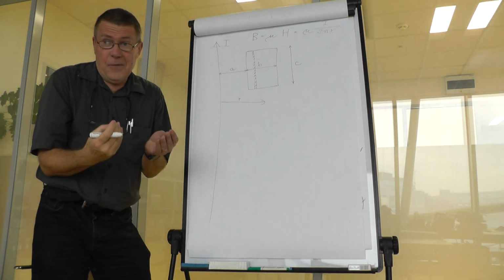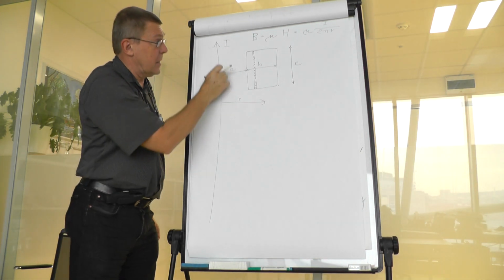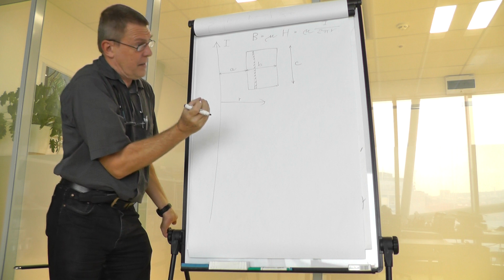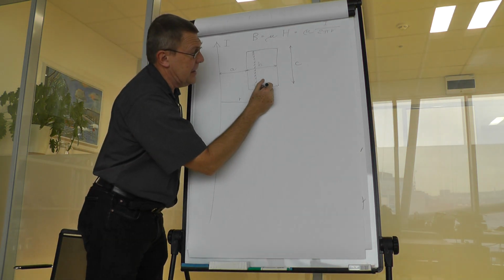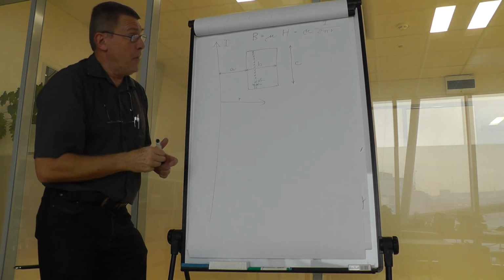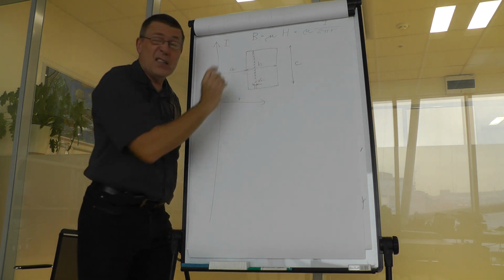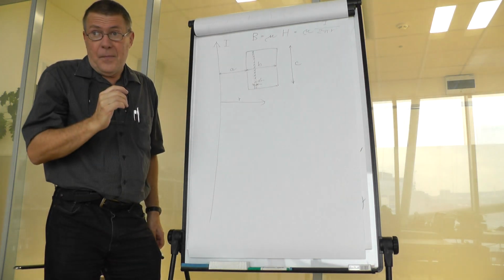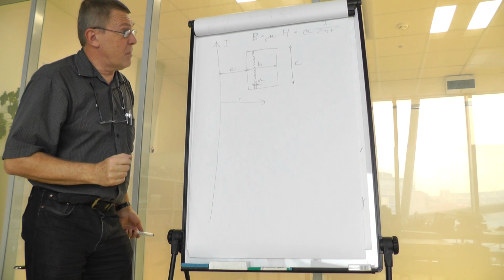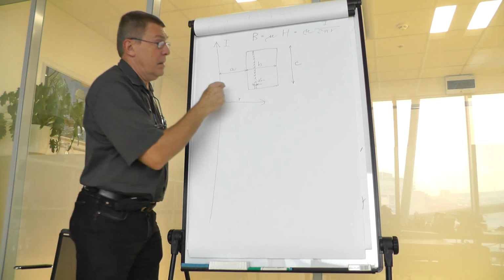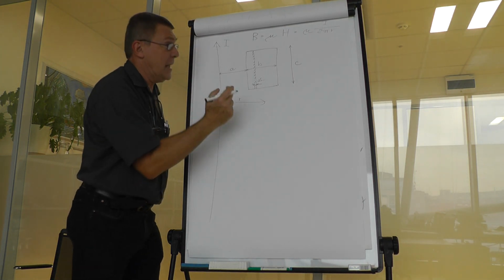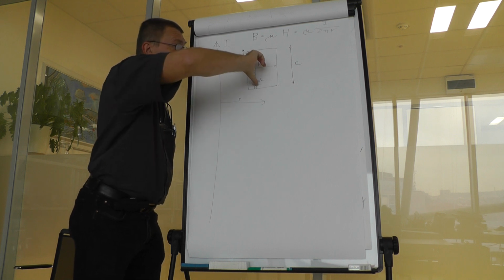That means it must have the same distance from the current that causes the flux. So this small piece, small rectangle, let's say, with the differential thickness dr, would have the benefit that the field inside it is constant, so that we can find out the flux through this small rectangle just by its radius r, the distance from the conductor bearing current, and the width and depth.